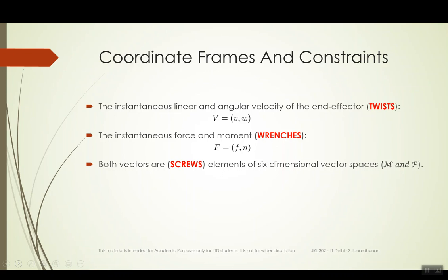by the manipulator, we bring in certain mathematical ideas. We bring in the ideas of screws. So the screws are six-dimensional elements, six-dimensional vector spaces. Okay, and the screws can be based on motion or based on force.